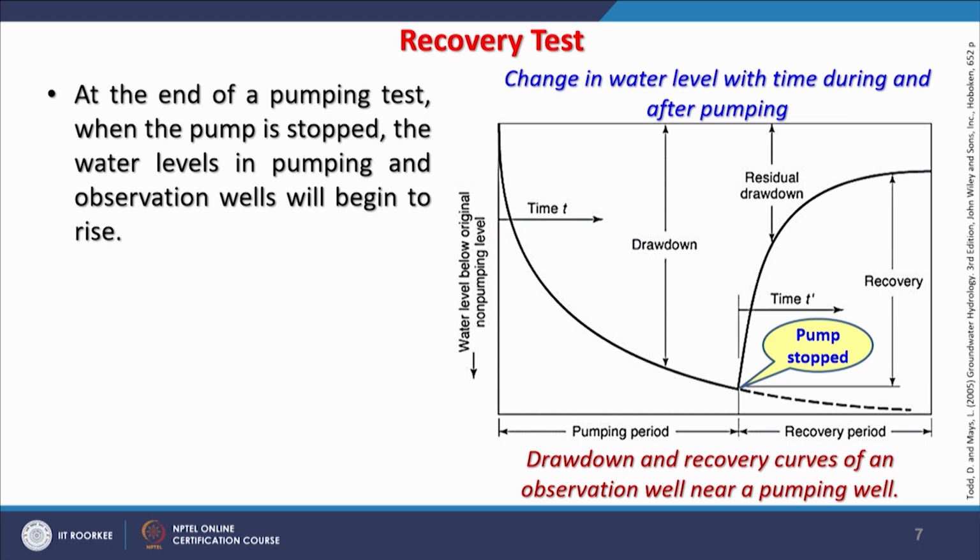Now, we have been doing pumping tests mostly. So, we will be drawing the water. In previous discussions, I have also mentioned that recovery tests are also done, that is how the drawdown is getting reduced or achieving the original level in the well, that is the water level in the well, and that will also give us values which should match with our pumping test values. Though recovery test may take a long time to note down the values and then try to understand the entire scenario.